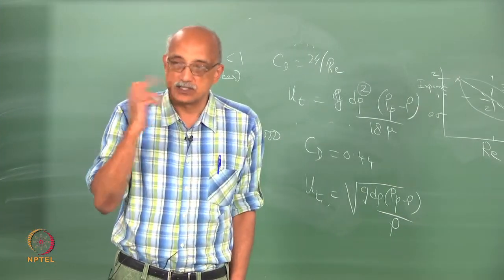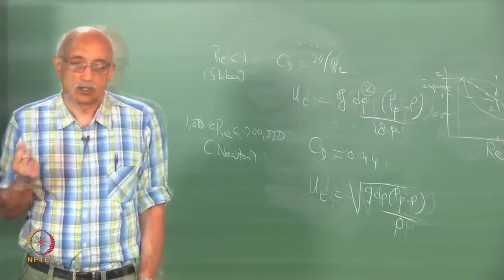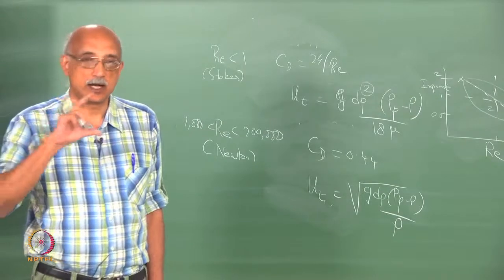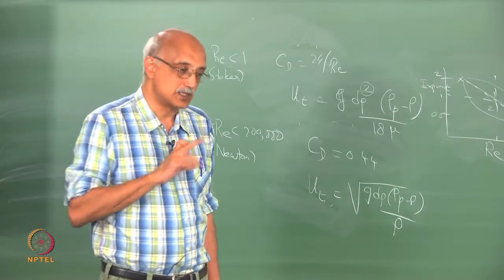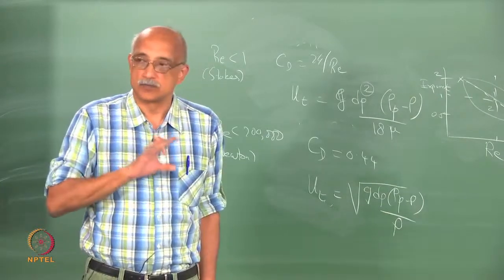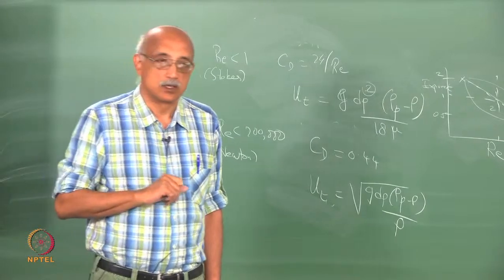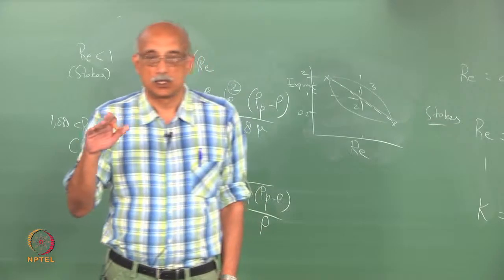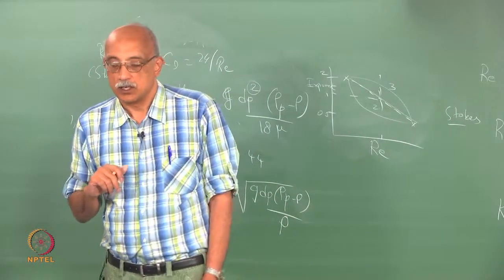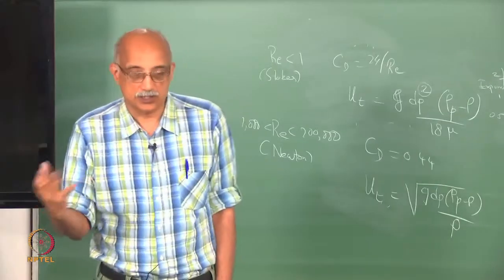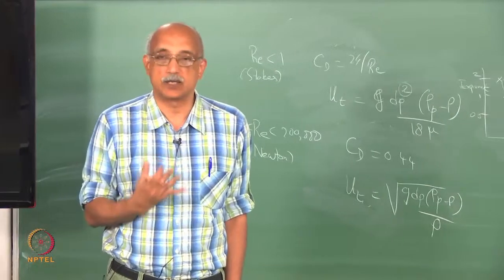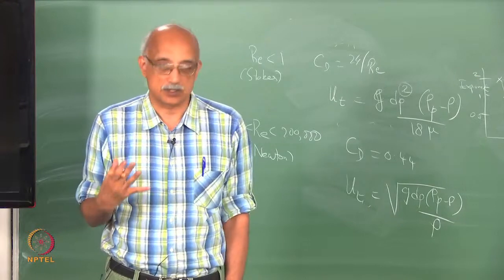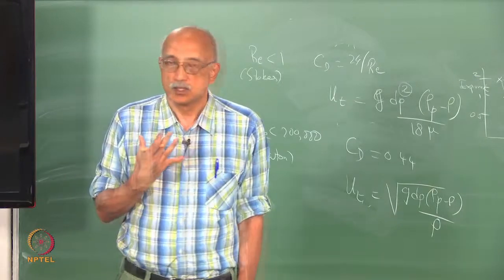But of course the design consideration is how do you manage the height of the bed? How do you essentially keep it operating in a steady state manner? How do you reach steady state and how do you maintain that in a stable state? And here is where the characteristics of particle behavior in suspensions helps us. It is essentially a self-limiting process or self-regulating process.